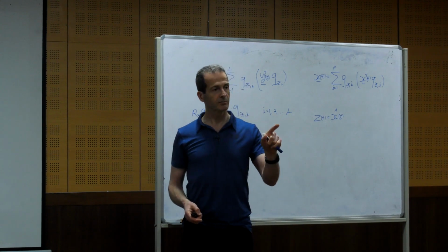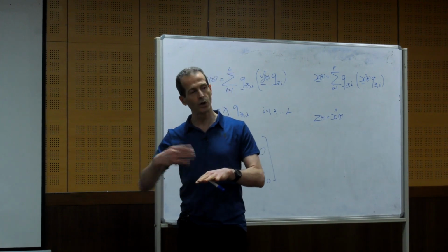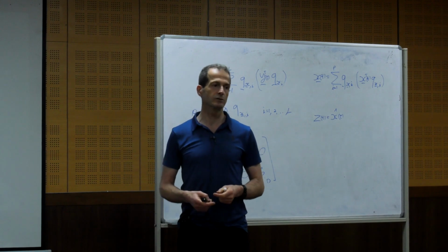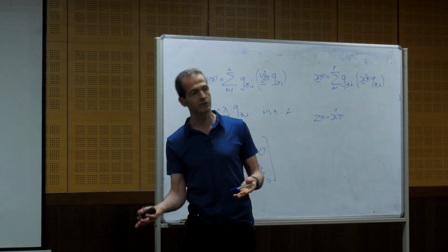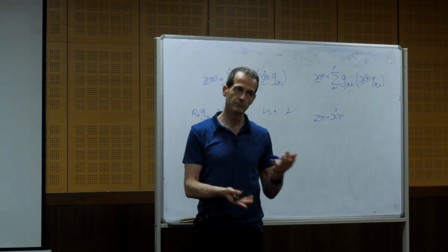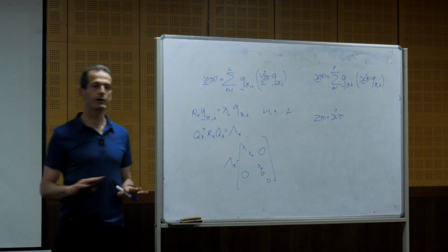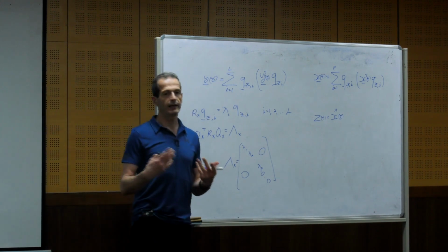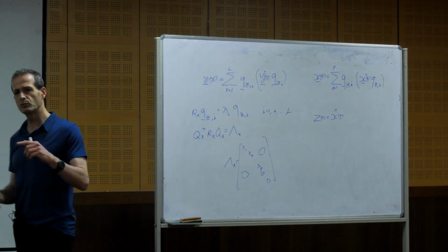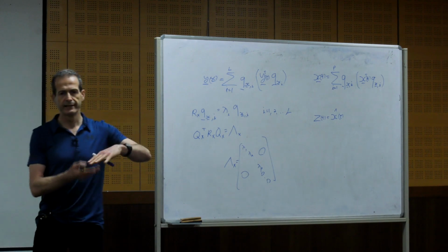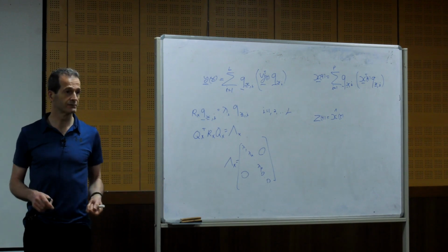With Wiener filter, yes, but the Wiener filter introduces distortion. So if you allow distortion, you can always reduce noise. And with the trade-off, it depends on whether it reduces more noise than Wiener or less, and this will depend on how much distortion you introduce. But the MVDR doesn't allow any distortion. That's why we need some subspace of noise only. It's just like with the Fourier transform. If the signal is present in all frequencies, then you cannot reduce noise. Okay?